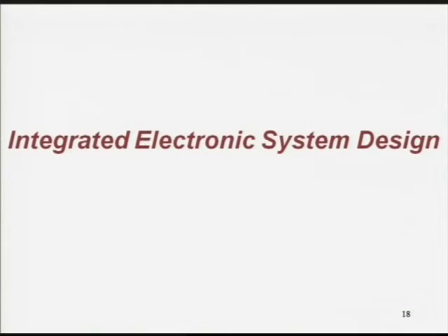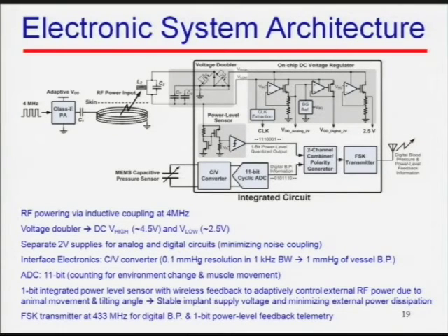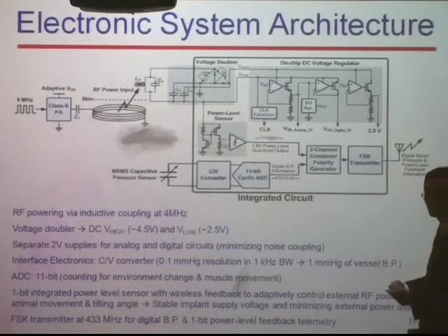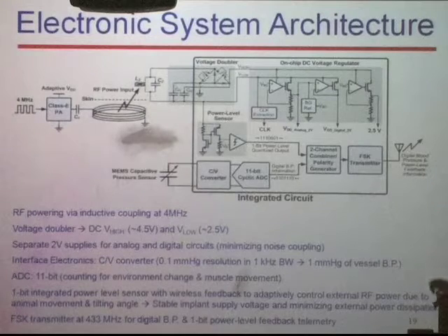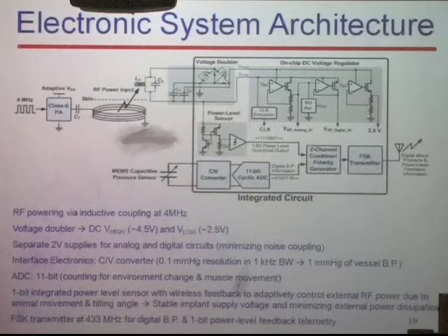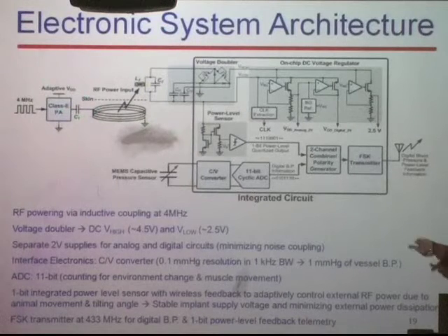So let's talk about the integrated electronics design system. This is a complicated picture, but I'm going to spend a few minutes to explain it to you. This is the design architecture. Let's start off outside. We have an external class E power amplifier, and there are well-established equations in the textbook for you to tune the L's and the C's. Some of you in this room are experts now, and can be much better than me at tuning these things.